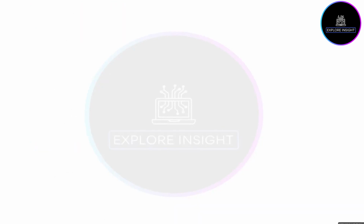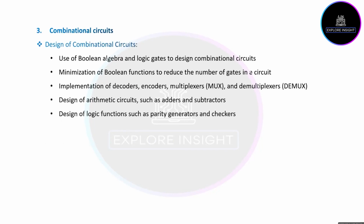Let's go to the third one, which is the combinational circuits. Combinational circuits are a type of digital circuit whose output is a function of the current input. The output of a combinational circuit depends only on the current input and not on previous inputs or the state of the circuit. In this case, we will consider the design of combinational circuits, which includes the use of Boolean algebra and logic gates to design combinational circuits, the minimization of Boolean functions to reduce the number of gates in a circuit, the implementation of decoders, encoders, multiplexers, and demultiplexers.